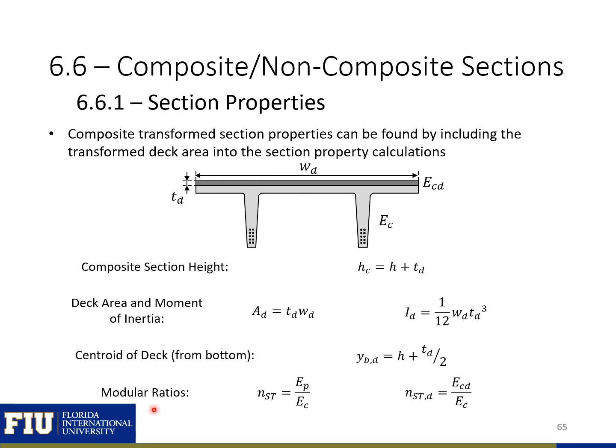We'll also need our different modular ratios, so I'm showing you 2 that we'll need here if we're finding our short-term section properties. So our short-term modular ratio transforming our pre-stressing, and our short-term modular ratio transforming our deck concrete.